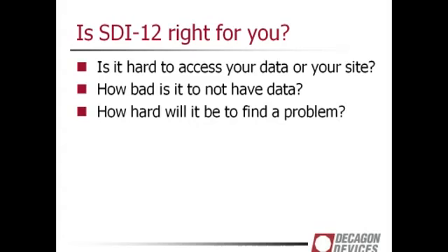Okay, some questions to ask before you go into SDI-12 to find out if it's going to be right for you. Is it hard to access your data or your field site? You need to be able to keep a close eye on your data. How bad is it to not have data? If you can't get to your field site for a few days and you have a sensor problem, how important is it going to be to lose all the sensors on that port for that problem? If every single piece of data you have is critical, SDI-12 might not be the best plan for you.